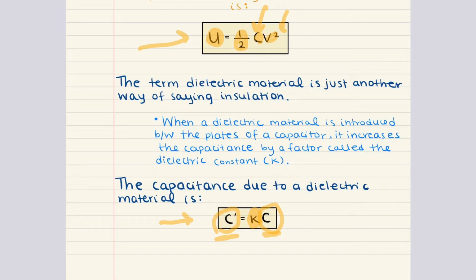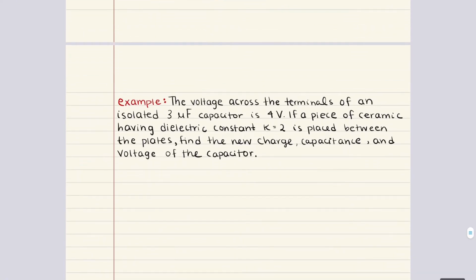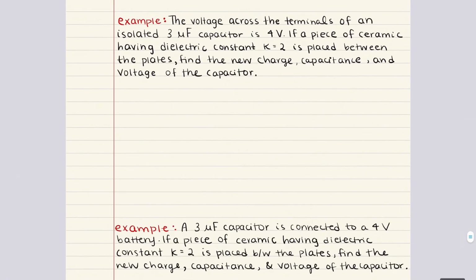The dielectric constant of a material measures how well the dielectric can reduce the electric field. Dielectrics allow capacitors to store more charge for the same voltage, improving their energy storing capacity. This is why capacitors in electronics often contain materials like ceramics, which have high dielectric constants. Keeping that in mind, let's jump into two practice problems.